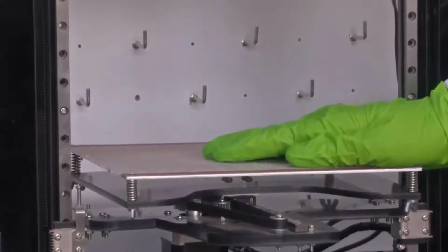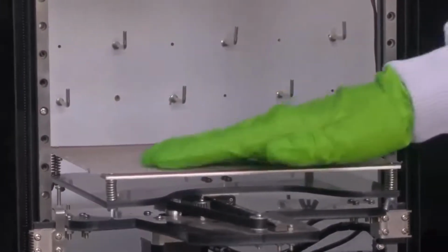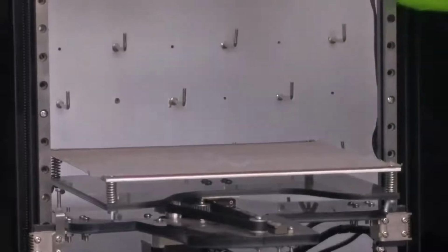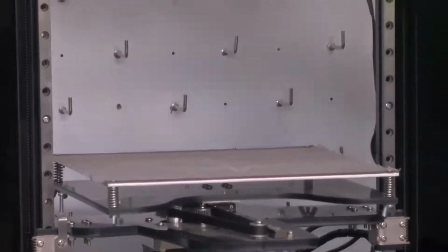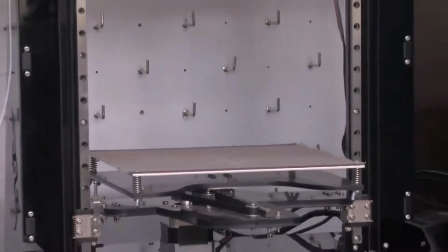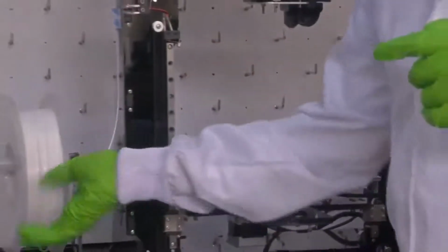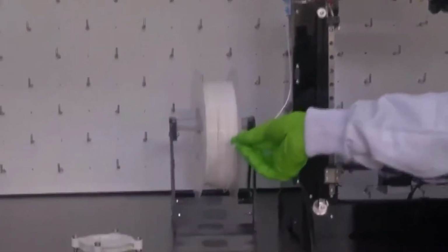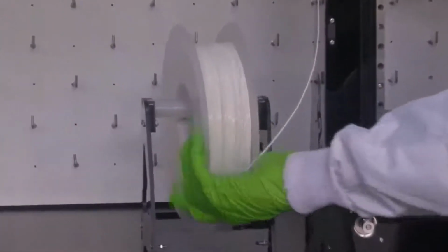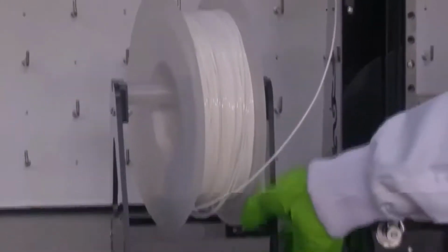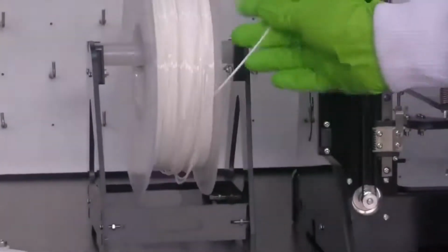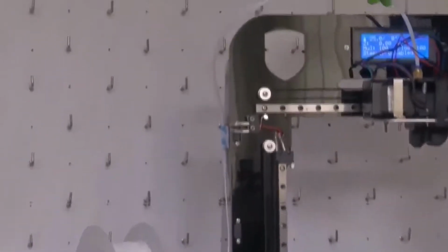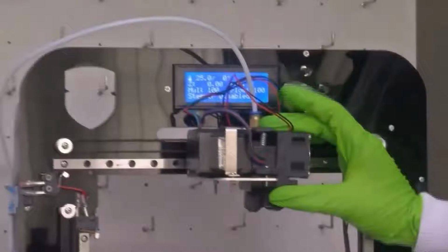Because your design will span the X, Y and Z directions, you need motors to control your material deposition. The material that we have used here is called PLA, polylactic acid. It's white in color here. You can see the material. The material is rolled up, and there is a lever that can hold the material in place. The material is like a wire here. It goes into this extruder. So this pipe takes it into this extruder here.